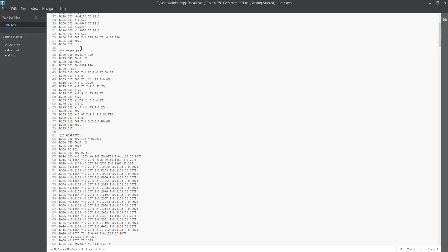The next one is the 2D contour, which is gonna go outside. And if you look in that one, you will see that one's gonna go that 250 down. And I think, the first time you're doing a new post, it's important to check this, not just throw some part on there. I know you wanna get things done and you are eager to get things done, but making a testing part like this is just crucial to make sure you don't crash your machine, to make sure you can sleep at night and all that stuff.